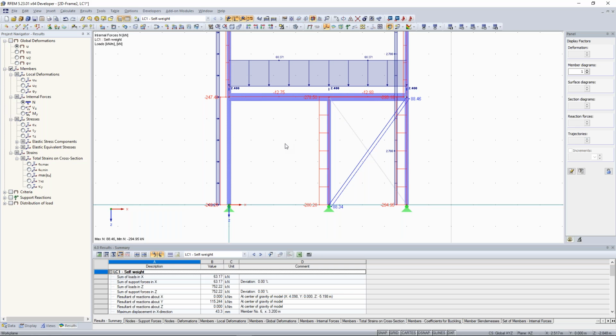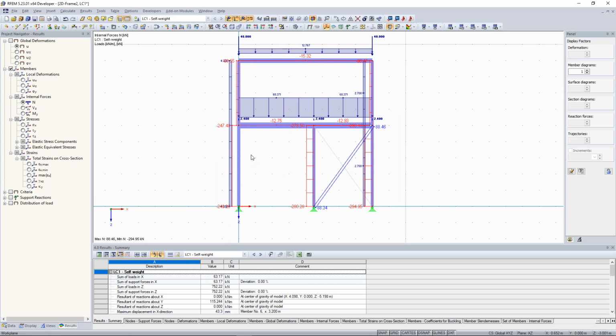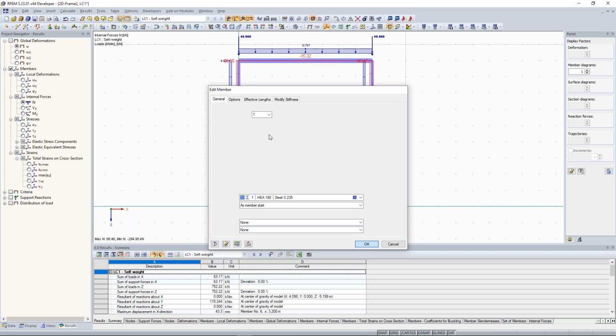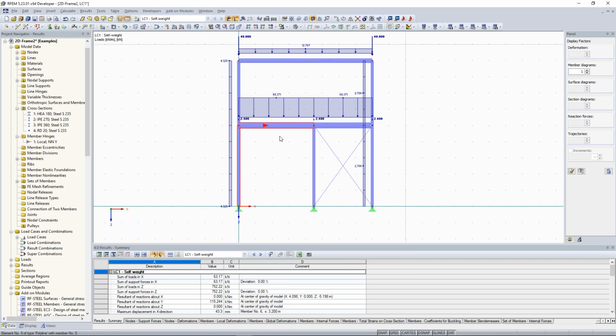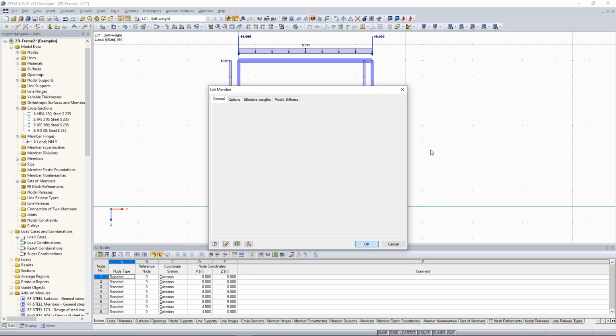Can you please explain how we can calculate the buckling length when making the unit checks using a stability module? So this is the next thing, making a buckling analysis. So for that, I change these again to normal beam here. Change this beam again to the beam, and the member start a hinge. Okay, now we have the situation before.